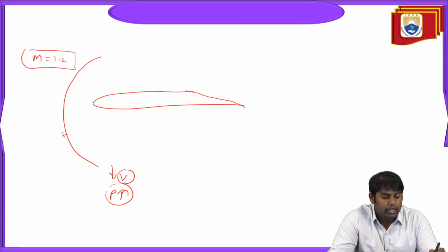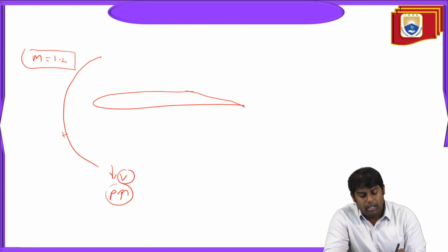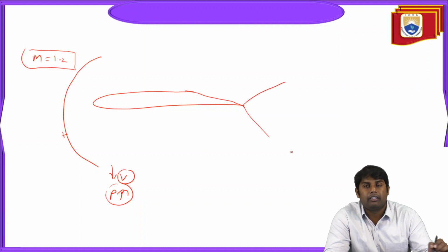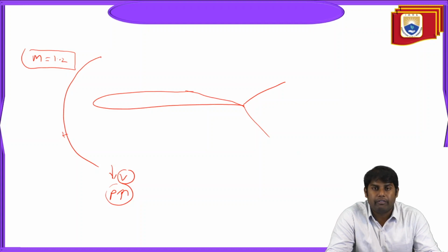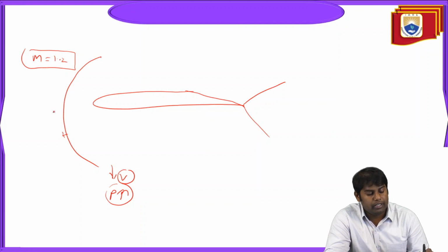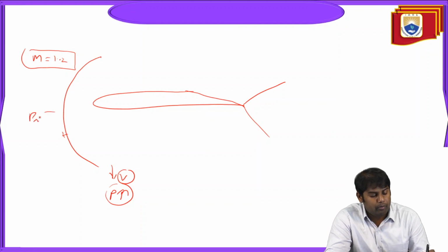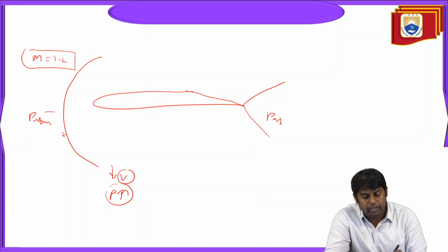When a shock wave is formed, it forms a wave drag which is pulling back, reducing the body velocity, creating an additional impact on the body. Here we have this, and at the tail you have this edge, an expansion wave. Here we have the shock wave, here we have the expansion wave, such that the pressure reaches P atmosphere.